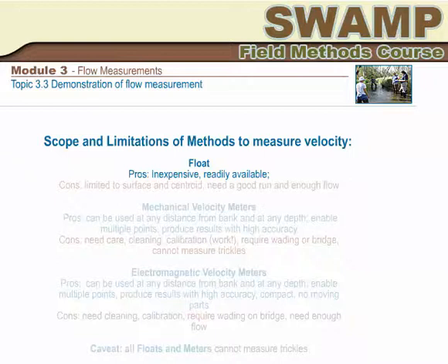The disadvantages are as follows. A, floats float. They cannot be deployed at a desired depth below the surface. B, a float does not navigate. It is carried by eddies, so it is usually not possible to control its course of movement in the channel. C, the method requires a longish stretch of straight channel for the float to travel at least 20 seconds, and that may not always be available.